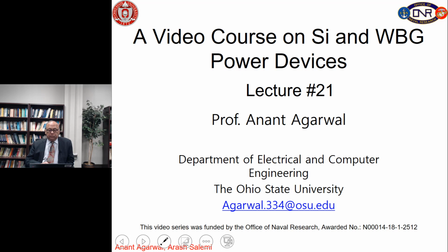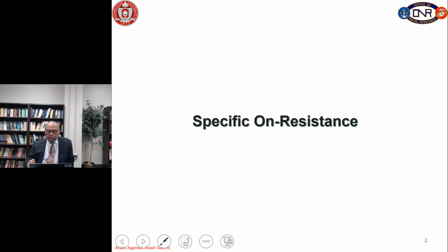So, today we are going to cover several topics on silicon carbide power MOSFETs. So far we have covered the basic MOS characteristics, the fact that inversion layer mobility is low, and then we have gone through a planar DMOSFET structure. And we have talked about the breakdown voltage of the planar DMOSFET structure for punch through mode and non punch through mode. And then we have talked about how to reduce the gate oxide field by moving the P wells together or controlling the doping and the width of the JFET region.